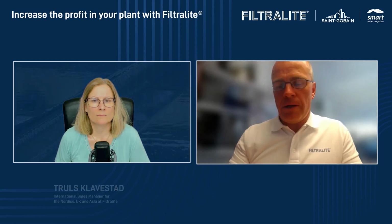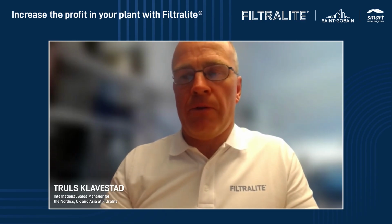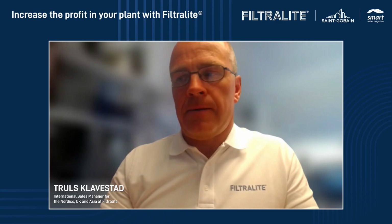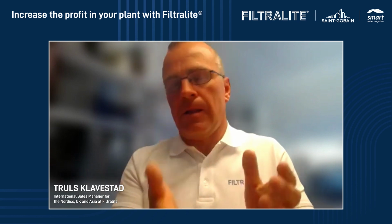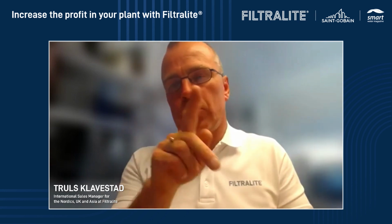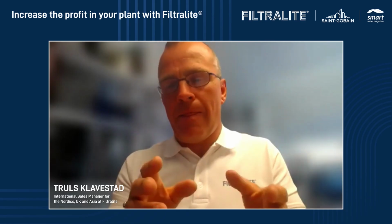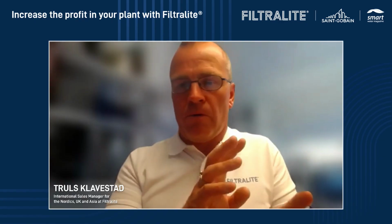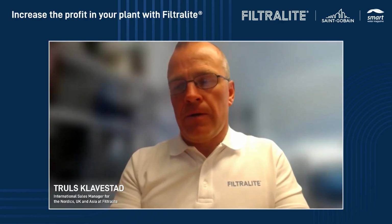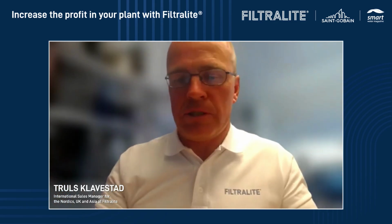Exactly what's going on, I cannot explain, but iron is the easiest to remove with Filtralite. As I said, if you take iron chloride dissolved in clean water, the iron is too small to be caught in the filter, but there is still something happening when you get the right bacteria, the biofilm, and also the kind of raw water coming in, then it just works, simple as that.